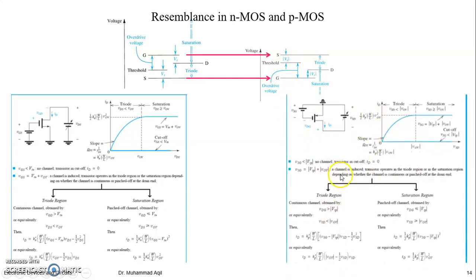So now this is the curve-obtaining equation. Here the polarities are fine, right? And you are having a curve here. Obviously it is VSD, not VDS. VSD is increasing, it means you are on the right side, right? But because this drain current is leaving, it means you must have a negative sign here to plot it on the first axis, otherwise it would be on the third axis.